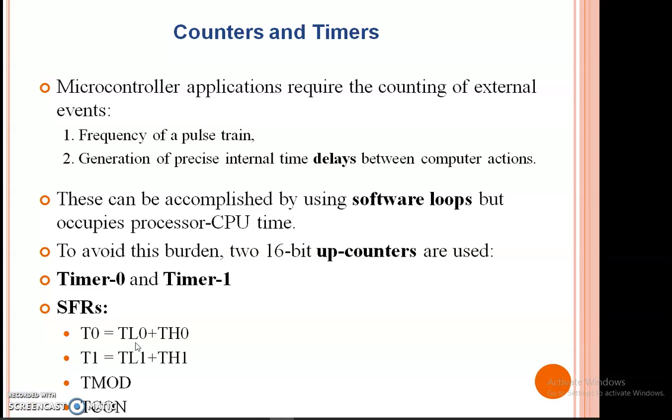Student, today we will learn about timers and counters of 8051. You know very well 8051 has two timers, timer 0 and timer 1, 16-bit timers. So what is the use of timers? Generally timers are used to produce delays, and to provide the frequency for serial communication. Serial communication requires a fixed frequency rate, which is also produced by the timers.